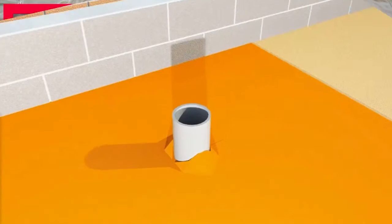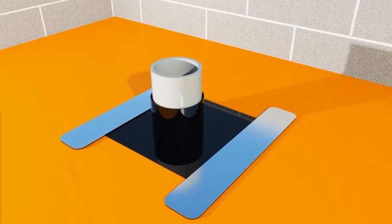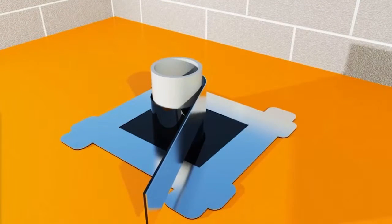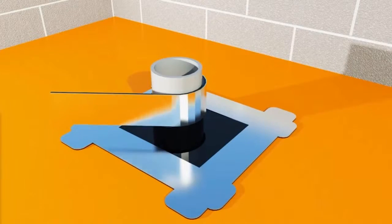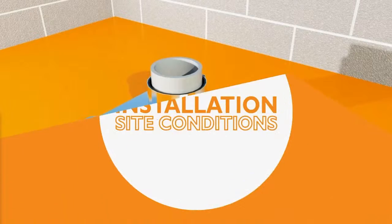Here we can see the correct procedure to provide a gas-tight seal to a pipe penetration. As with columns, this is not particularly difficult to achieve. Again, as with stanchions, ensuring the membrane is cut as little as possible and the top hat is smoothly seated onto the membrane is critical. The flashing tapes should be firmly adhered in place and properly supported.